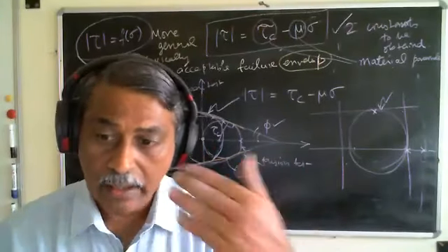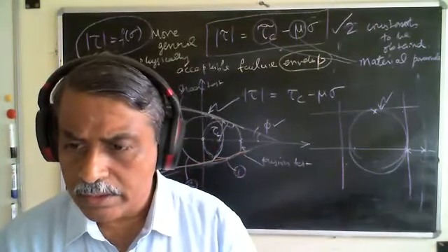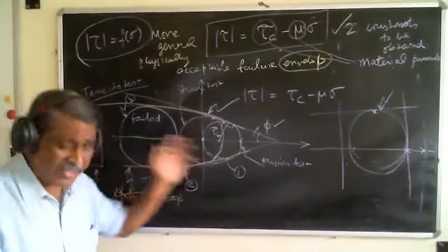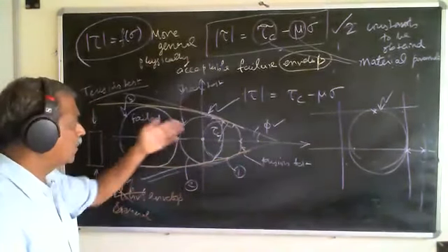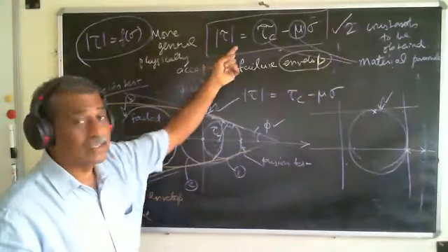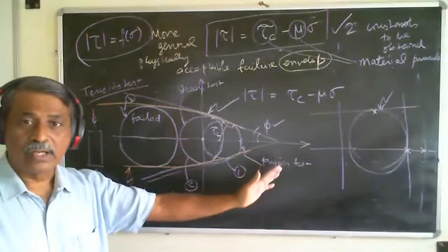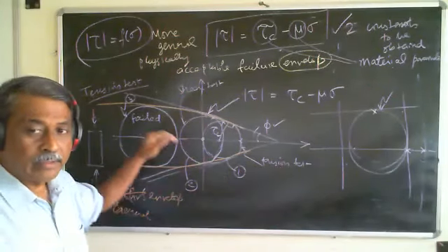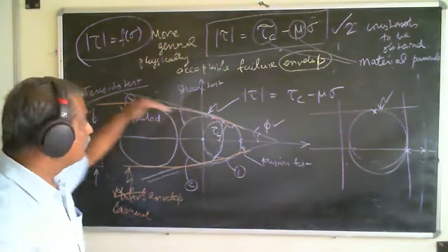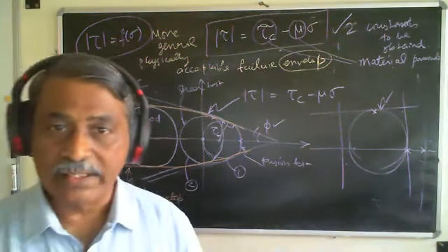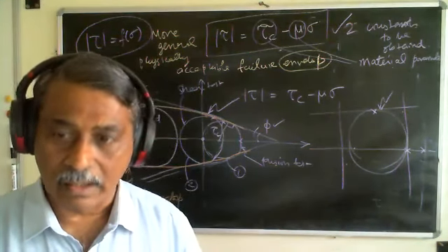Later on, we'll come back. So the general equation is this. If I conducted many tests and this kind of discrepancy occurred, then I'll say, let me put all those Mohr circles for which I have done the experiment, and have the envelope in such a way that it covers all the circles of the stress states for which failure occurred.